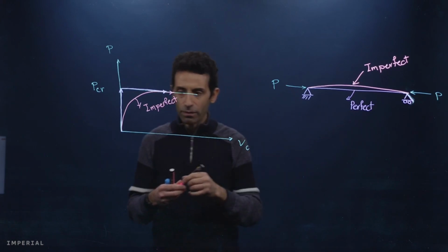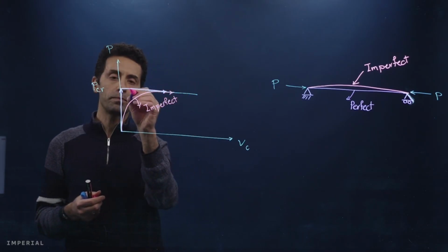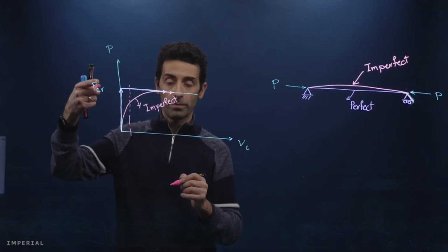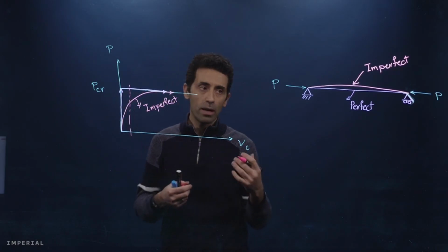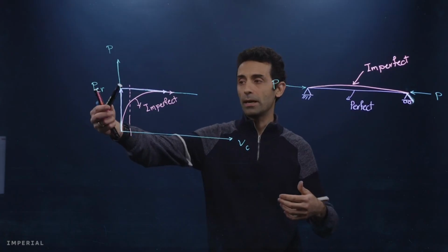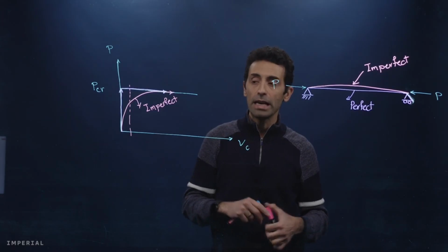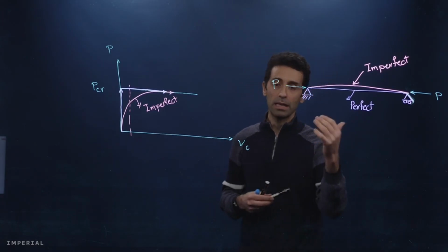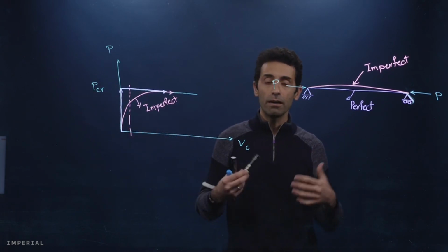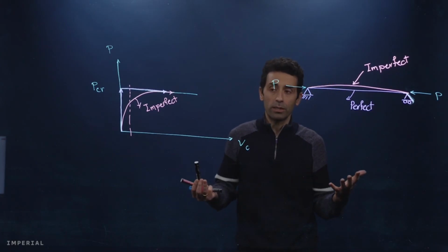So you can see that if we are, for instance, looking at a certain amount of deflection in our beam, like here, the pink one is happening before the purple one. That would mean that this amount of deflection would happen before your structure even starts the bifurcation or buckling based on the linear theory. In other words, by using the linear theory, by using the relationship to find the critical buckling load, we are overestimating the failure load of our structure.